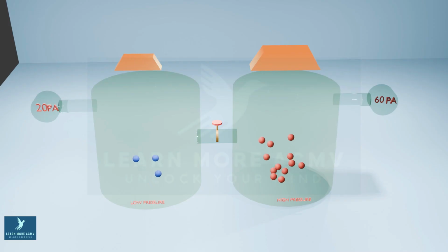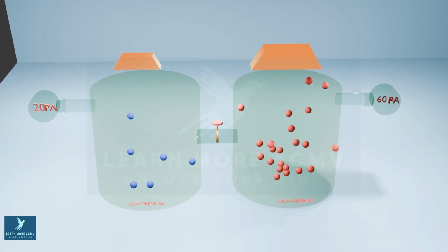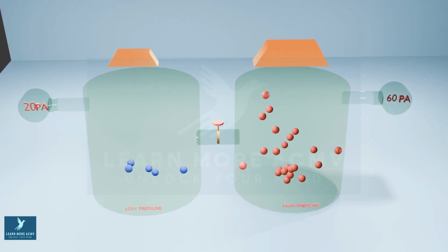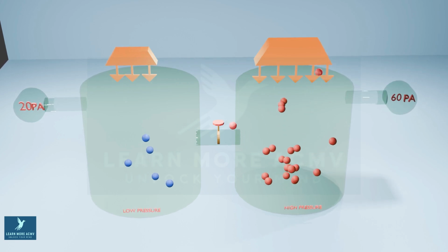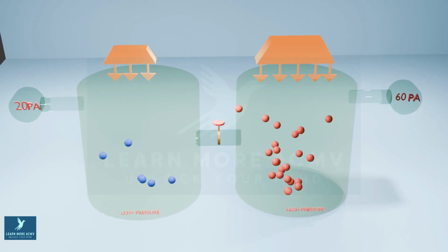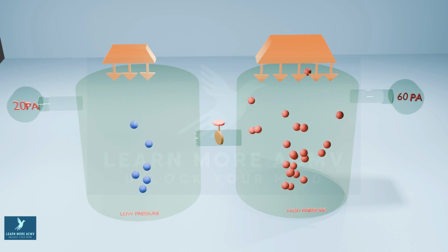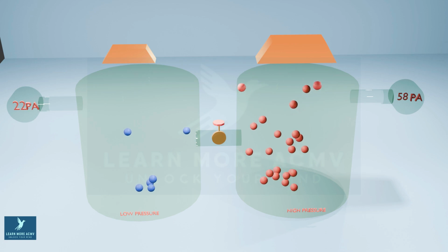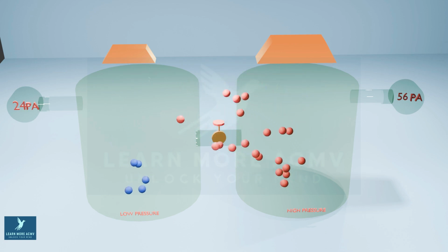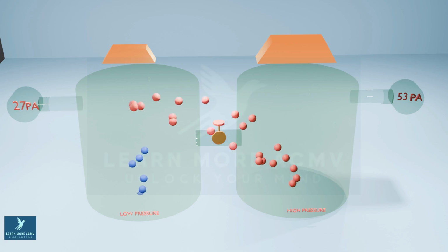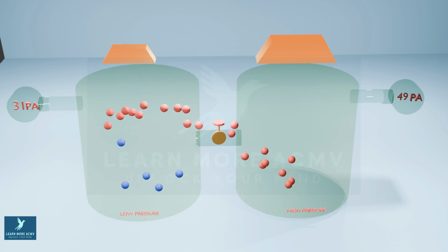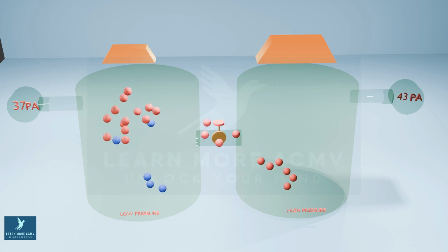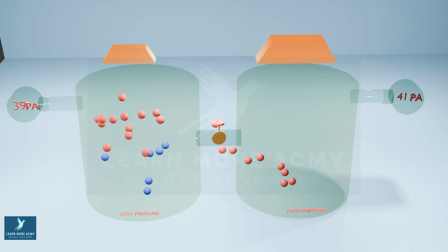When one side of a space has higher air density, meaning more air molecules packed into that area, the pressure becomes higher there. The other side has lower density, so the pressure is lower. Because nature tries to balance pressure, the air moves from the high-pressure side toward the low-pressure side. This flow continues until the pressure becomes equal on both sides. This is the key principle behind ventilation, exhaust systems, and all HVAC air movement.